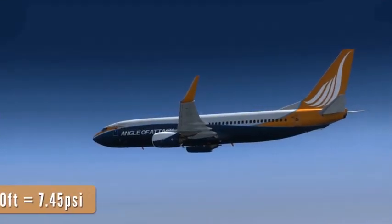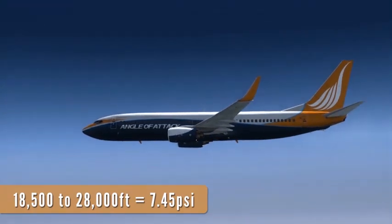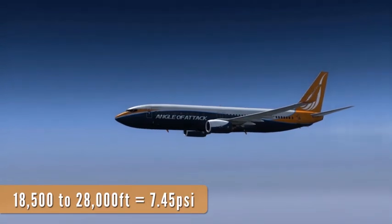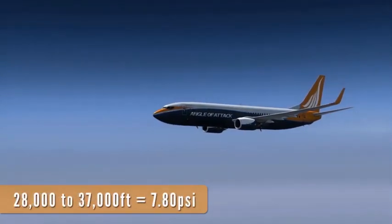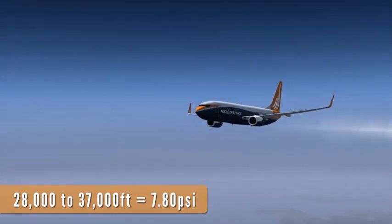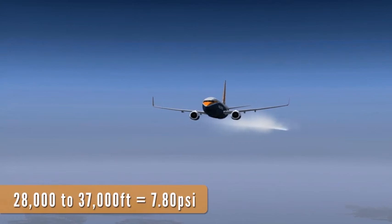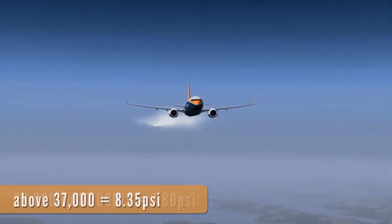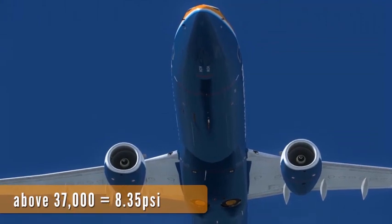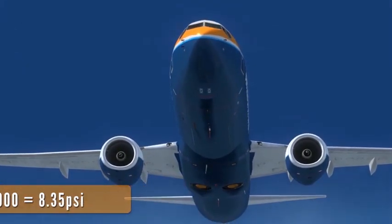If the flight occurs between 18,500 feet and 28,000 feet, the target pressure differential is 7.45 psi. If the flight occurs between 28,000 feet and 37,000 feet, the target pressure differential rises to 7.8 psi. Finally, if the flight takes place at or above 37,000 feet, the target cabin pressure differential becomes 8.35 psi.